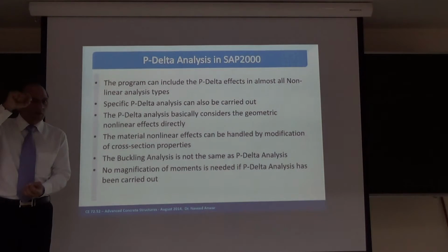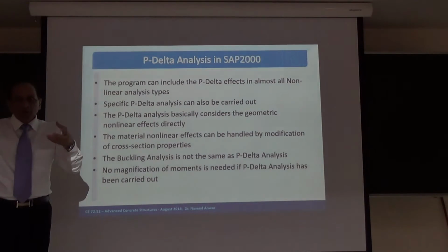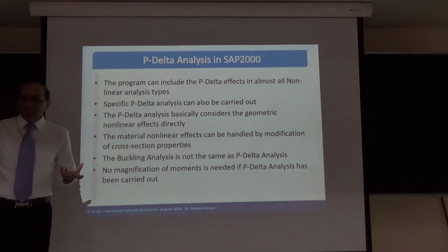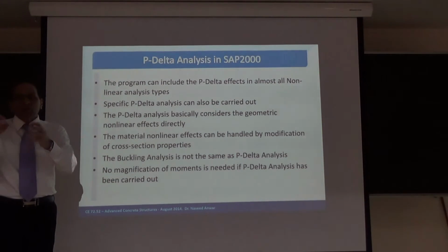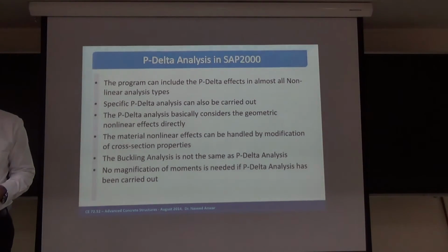So when you apply the load, they always have a little bit of moment, or the load is applied slightly off center. Because how can you apply the load in the center? There's no such thing as a point load. You have the beam coming here, beam is connected, beam is causing bending. So in all cases, column is subjected to bending.